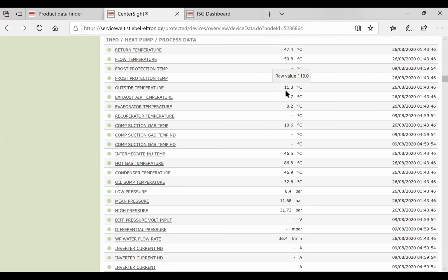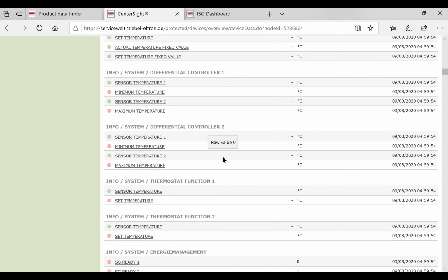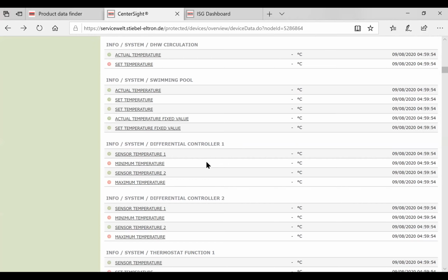And I can see if it's recirculating, I can see there's a difference of 5-6 degrees, and we can give the installer, or somebody, a good indication of what the efficiency loss is because I've installed this thing with grills across the front of it, in an enclosure instead of in fresh air. We can say, right, well, you're dropping 5 degrees of ambient operating temperature on average for that unit. And a 5-degree ambient difference on a WPL 25 might be a COP of 0.5 or 0.6 or something. We can measure that stuff.